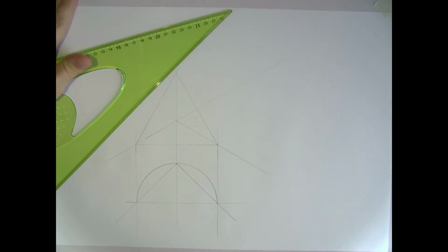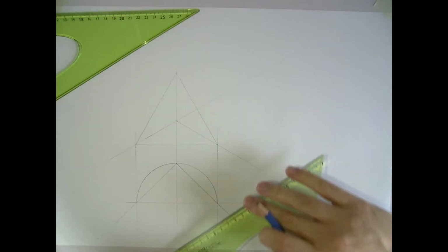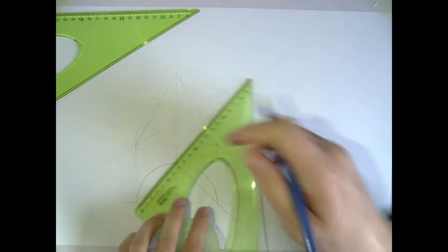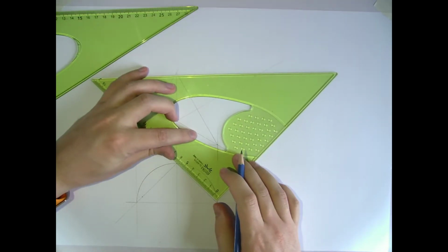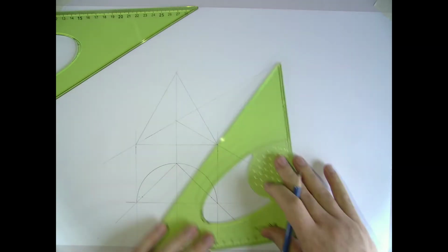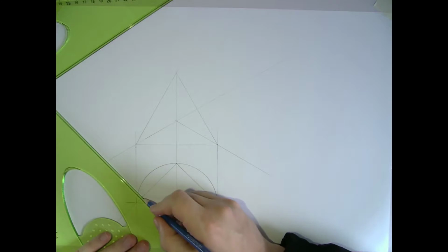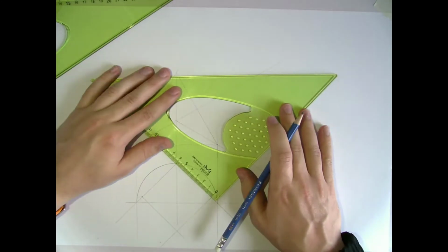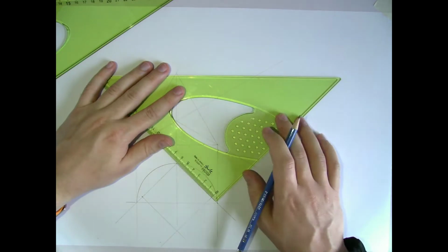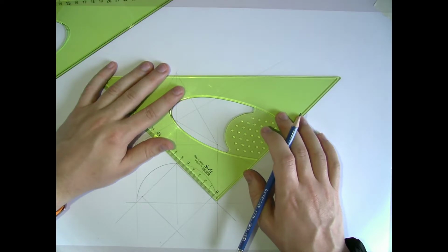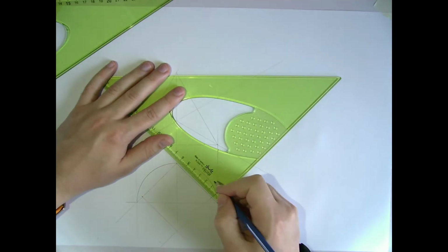So I'm going to draw the plan now, and it's based on a rectangle that's 60 by 60. And then the inner part of that is based on 40. So the inner square is 40 millimeters, and we can see that information up in the elevation view, up in the top right. So that 40 there is where that's coming from.